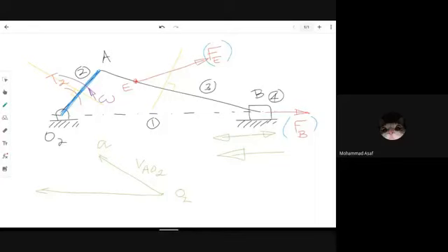And now for the velocity vector of AB, we have already drawn a perpendicular like this. So parallel to that perpendicular, I'll draw a line segment from here. Now both will intersect at this particular juncture, and this is given as the point B. So O2 to B will be the velocity of B, the fundamental velocity of B. Then the direction A to B will be like this.